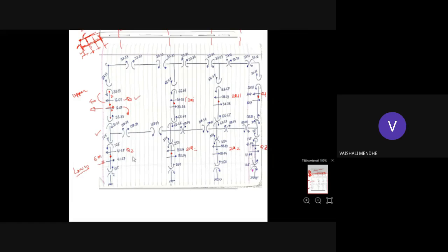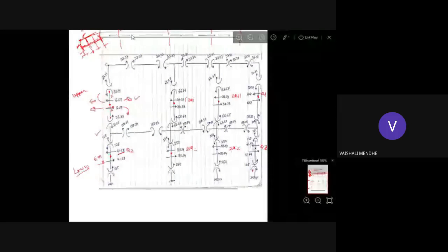Okay, you have to look at the height. Here, the horizontal shear for this exterior column is 41.67. So 41.67 into 3, you'll get 125. So that is again in the anti-clockwise direction.